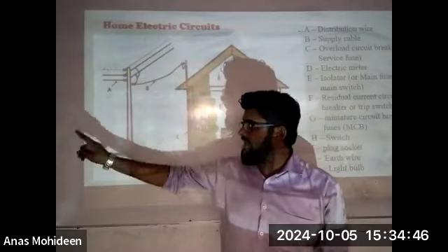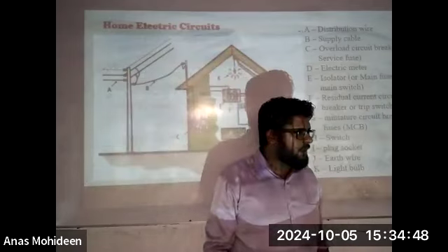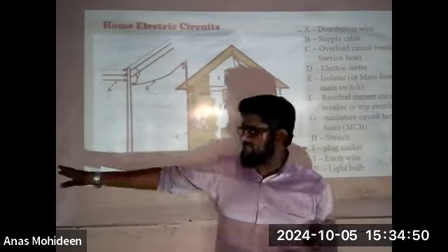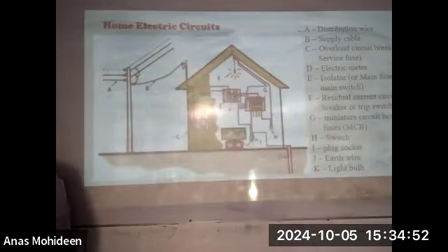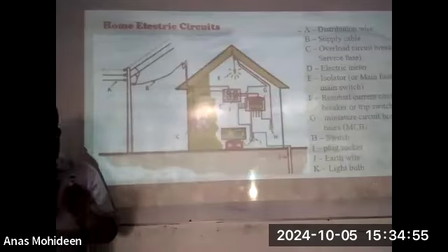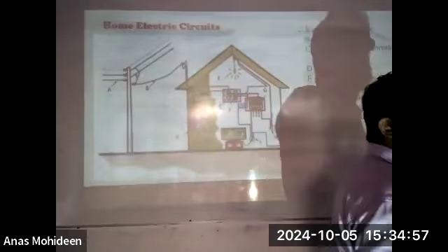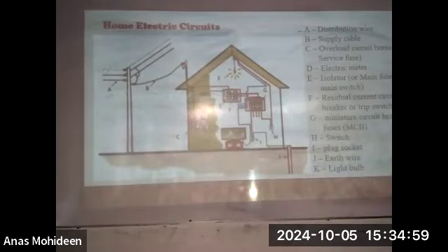So even these wires, when we are taking them, you can see it's wrapped up, it's covered up. So this is actually the complete wire. Inside, usually we have two wires. When you are taking the two wires, the wire which is covered by red or brown color is the live wire. The one covered by either blue or black color is the neutral wire.